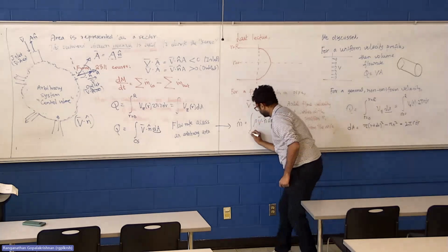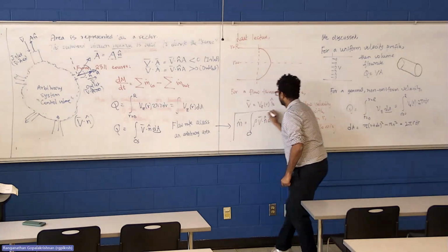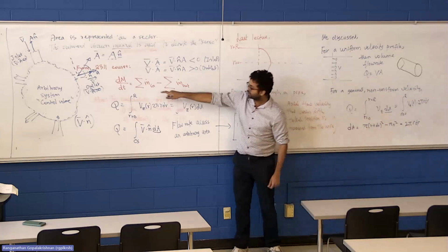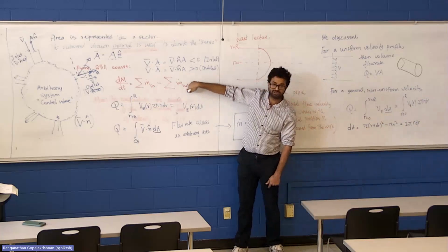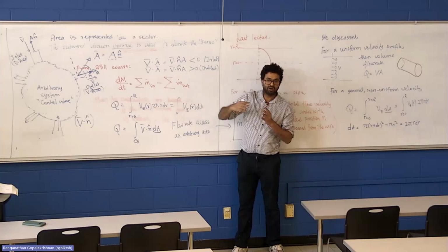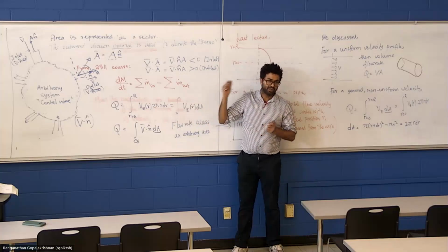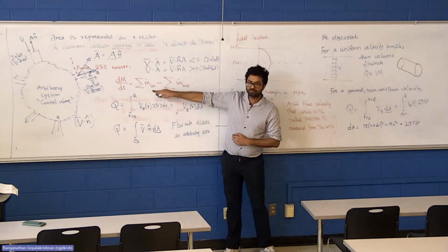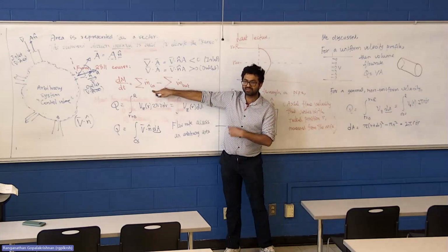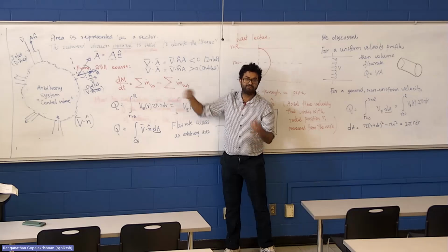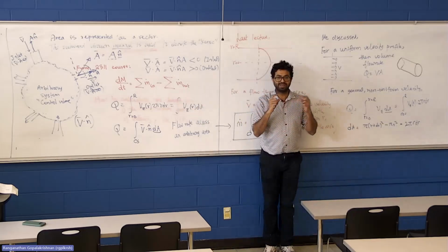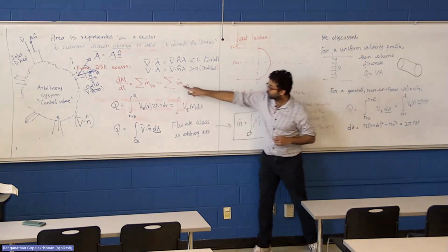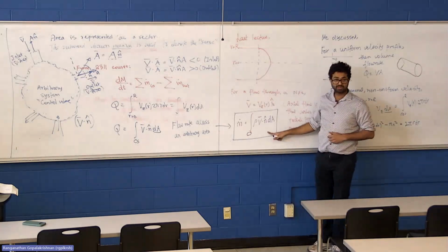But this expression is what you really need to be able to write down to calculate the mass flow rate across a cross section coming in or exiting a control volume. The big difference is that in thermodynamics, they always told you how much mass is coming into or leaving a system. They gave you a number directly. In fluid mechanics, we don't directly handle the mass flow rate, we handle velocity, and from velocity we compute the mass flow rate, and that's how you compute this.